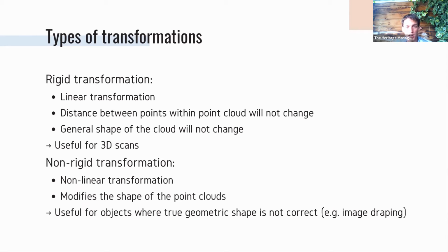And even if we change them, like in photogrammetry, we will use a "vormgelijkheidstransformatie", a deformation in equal direction. So if we apply a scale on the x-axis, we also apply the same scale parameter on the y and on the z-axis. But most of the time, of course, the scale parameter is something we will not touch. We will only translate and rotate our point clouds because our measurements, especially in laser scanning, are a priori correct.